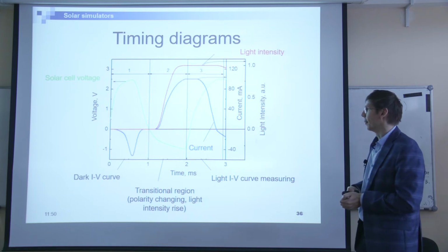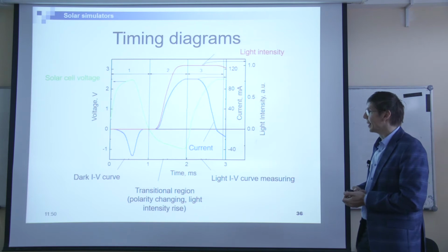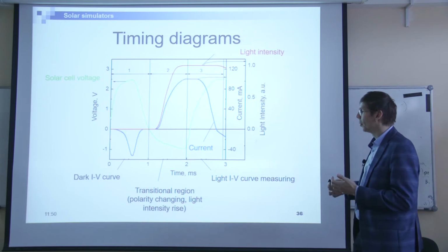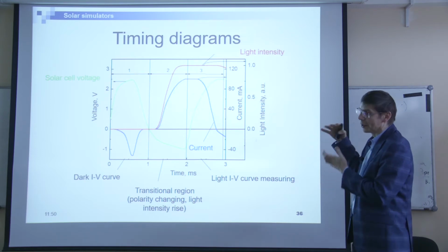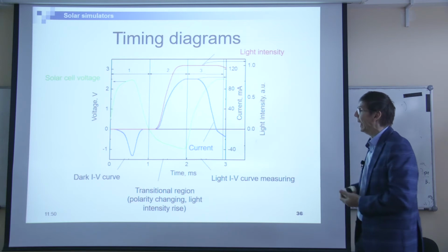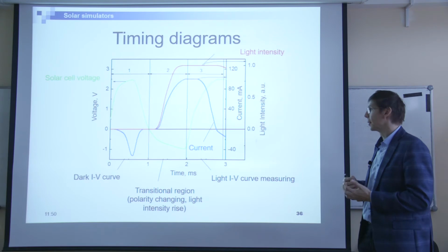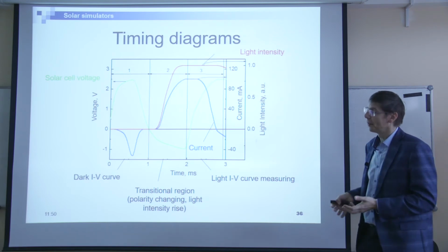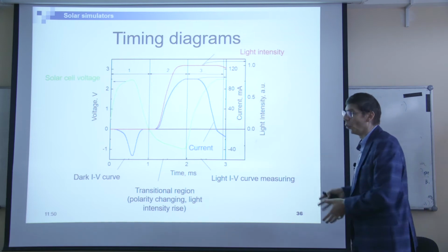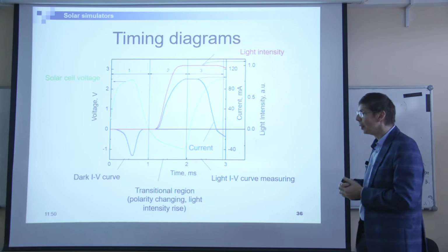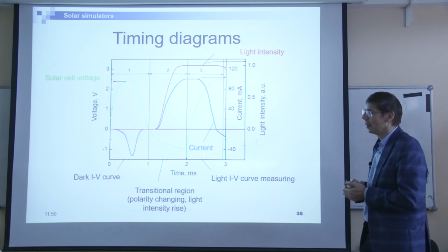You have a huge increase of the capacitance with the voltage, and this capacitance depends on the thickness of your base, so the thickness of the active area, and on lifetime. So there are two main parameters. For III-V, normally the lifetime is quite small compared to silicon, and the thickness is quite small, again some few micrometers. So the diffusion capacitance is even negligible.